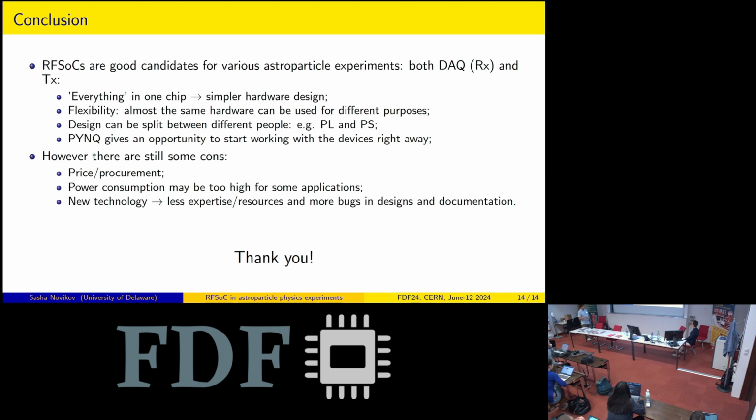So for instance, what we do, some grad students work on the PS side, so they work on Pink and then do all the tests. For instance, you run a board as a network analyzer right away. So basically you just create a bit stream, give it to someone, and they can use the devices to check the performance of a filter or an amplifier, etc.